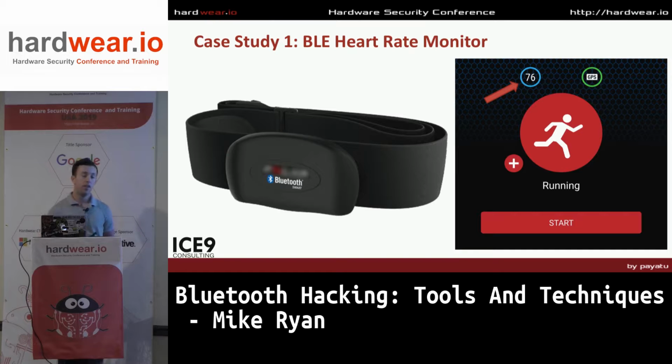Step 1, do something in the device, do something in the app, and make a note of what we're doing. So in this case, we're going to put on the heart rate monitor, and we're going to tell it that we're running, something like that, and we're going to make a note of this heart rate value here. In this screenshot, the heart rate is around 76. We're going to have the Android OS logging the Bluetooth HCI data in the background. Then we pull that data off of the device and we load it up in Wireshark.